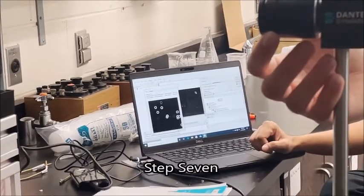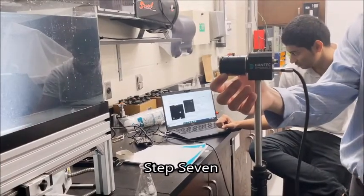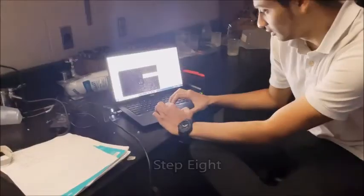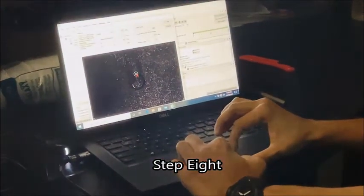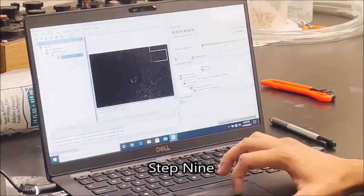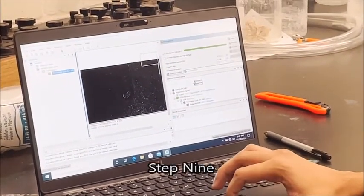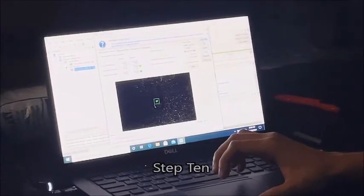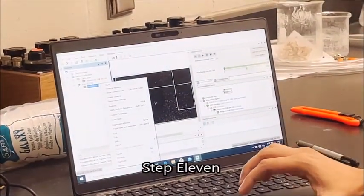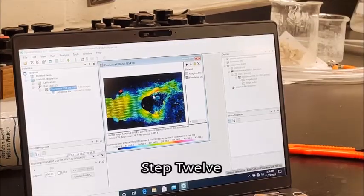Adjust the focus and aperture of the camera to capture a particle density of approximately 15. Capture a single image to specify the scale factor. Adjust the sampling rate to around 130 Hz and input the number of images desired. Acquire the data and save it to the computer. Right-click the data for analysis options. Finally, view the results.